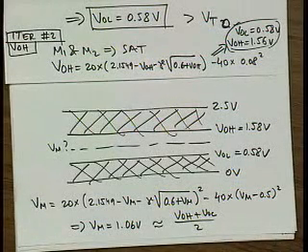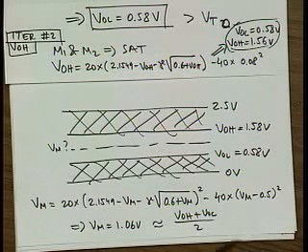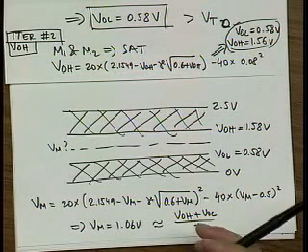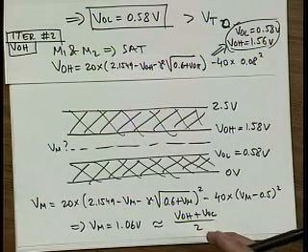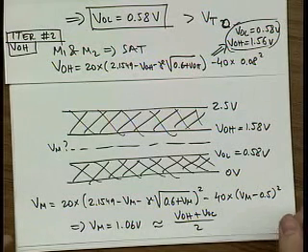Now, for the first approximation, if you don't know where to start, you can use VDD and ground to compute the initial values of VOL and VOH, and that's what the homework solution suggested. But you have to really go one more or a couple more iterations to get accurate answers. Question? Absolutely, yes. Calculators are allowed on the midterm, but you won't have anything of this complexity. This is just basically to make sure you really understand what's going on.